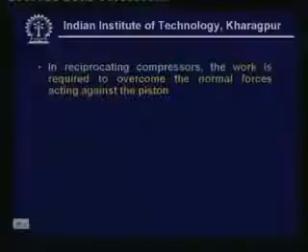And in reciprocating compressors, the work is required to overcome the normal forces acting against the piston. So why do we require work input in reciprocating compressors? If you think about the working principle of a reciprocating compressor, when the piston is compressing the refrigerant, it encounters a resistance by way of a normal force, and this normal force is due to the pressure acting against the piston.